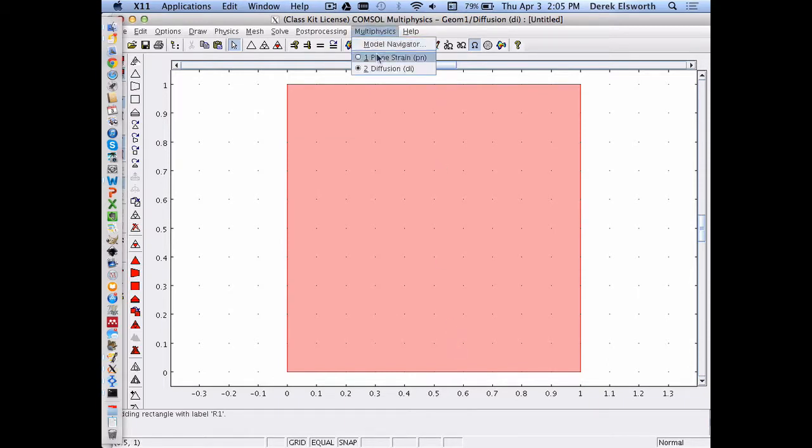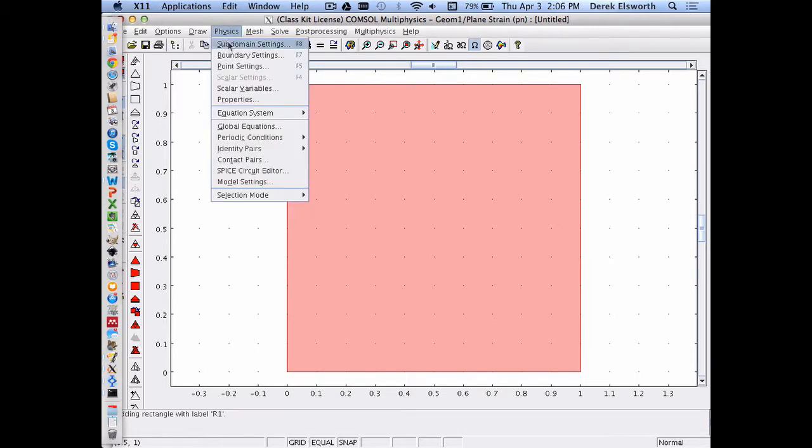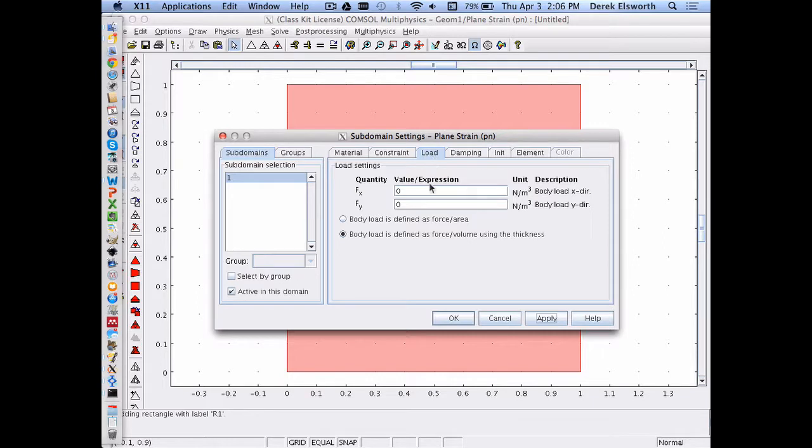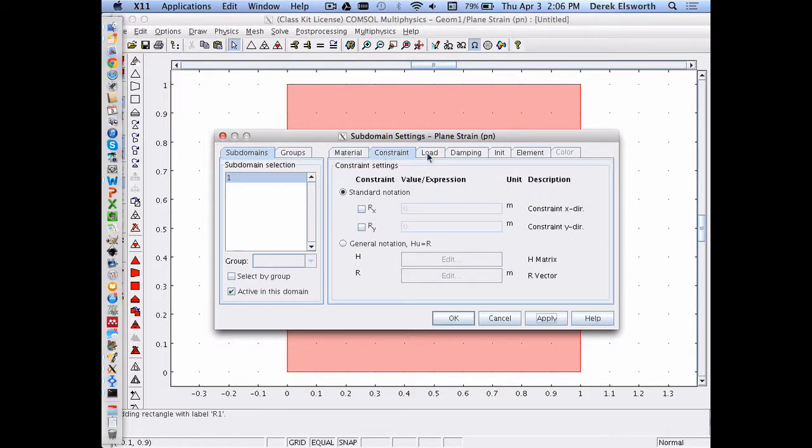And the complementary part is the plane strain part. And we would want to go in and do exactly the same things. So this is the behavior we've got. Modulus, we said, was 1. Poisson ratio, we said, was 0. Density, I think it's probably not a problem if it's weightless. It might not like it, but it's probably okay. And constraints. So this is the body force. It doesn't give the equations here.